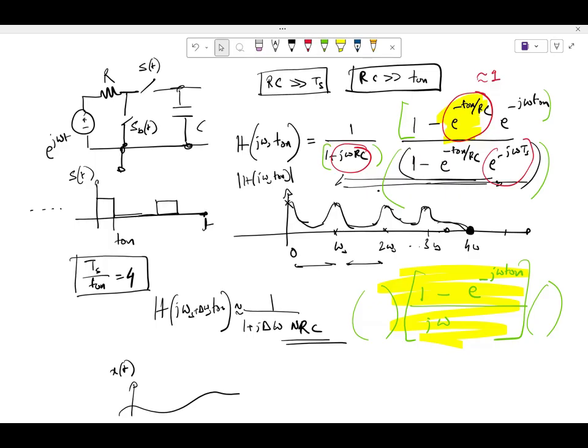So which means that regardless of whether you are looking at it at off time or on time, the value that you see across the capacitor is almost equal to the value accrued by the capacitor on T on. As it turns out, the value accrued by the capacitor on the T on is the integration, the average over the cycle. That's what we showed here. And it keeps on holding on to that value for extended period of time.